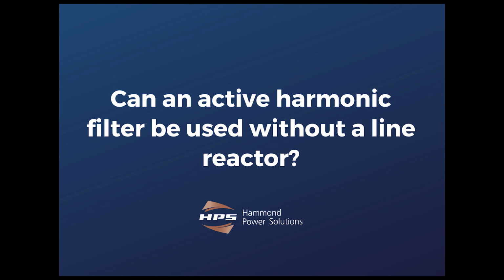I'd like to add that many small VFDs, depending on the manufacturer, might be 20 horsepower and below or 10 horsepower and below, may not contain a DC link choke.